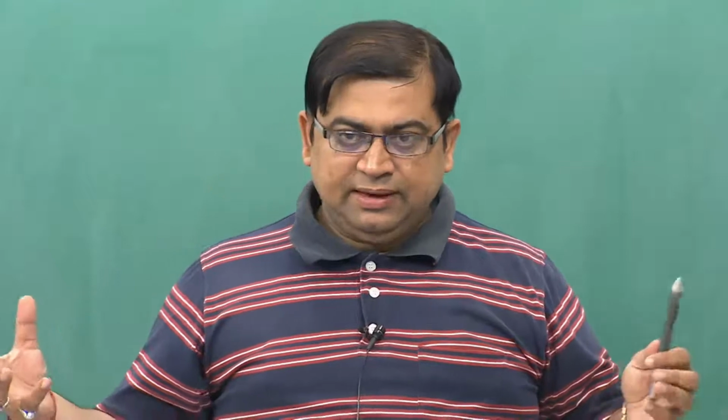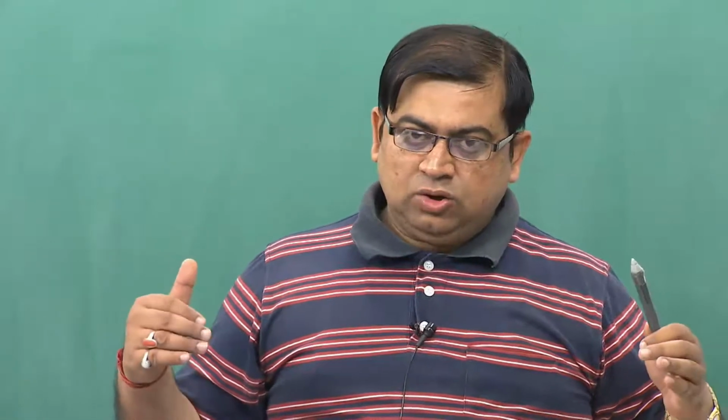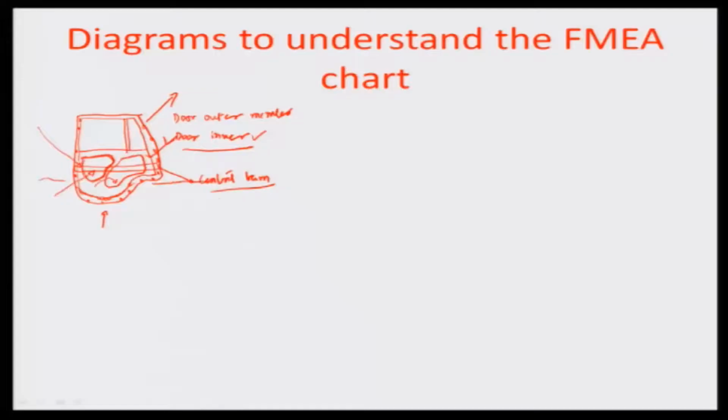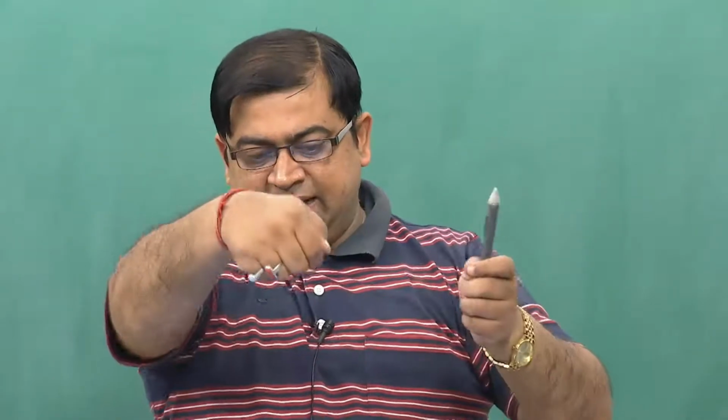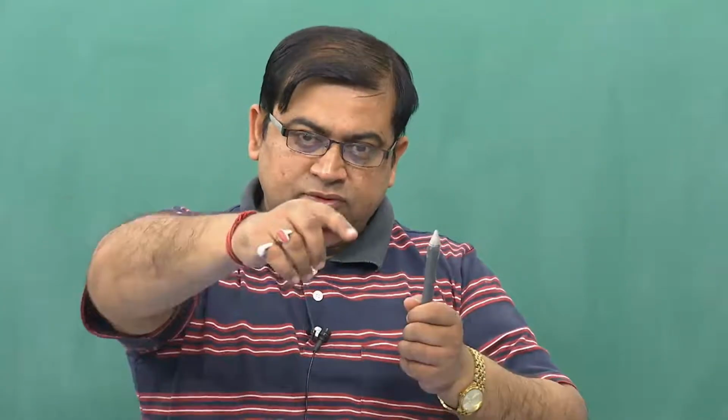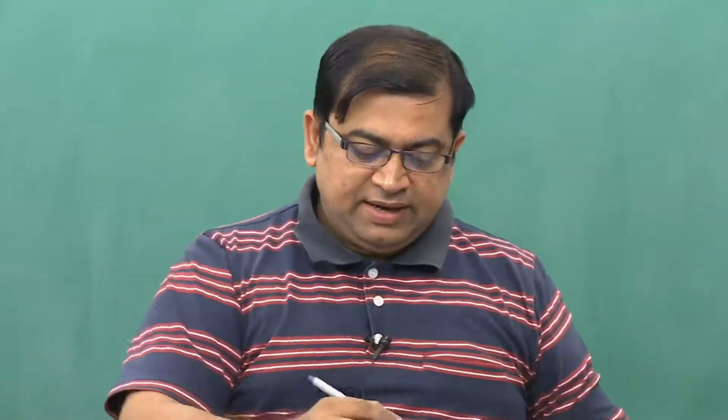Or even during, let's say, rainy season, there is a case where the automotive goes in a submerged manner, and a part of this door is already submerged in water at this kind of a level. So you have to ensure that even though there is a hemming between the inner and outer members, there is going to be some kind of waxing in the inner member which would prevent such a thing from happening. So the idea is that if this is the thickness, where this is the outer, this is the inner, you have to go from the inside, and in between the two you have to give the wax coating somewhere in the middle.